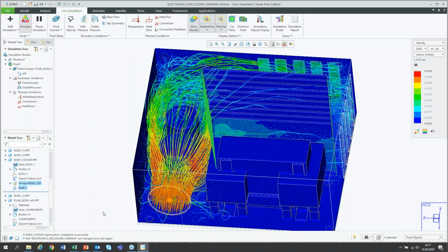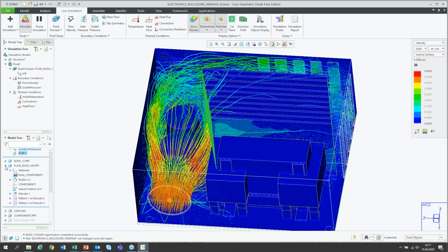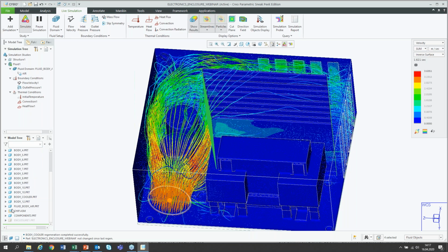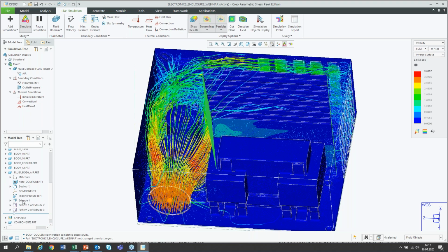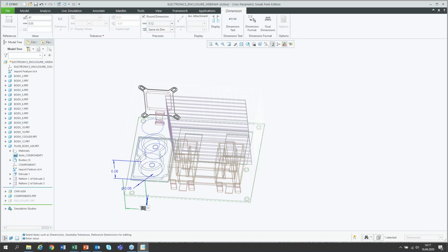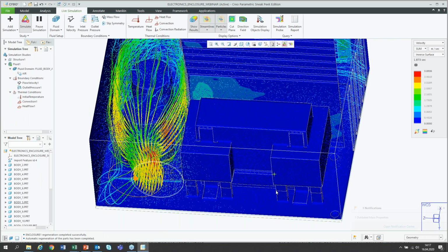And now I'd like to move the inlet here. This construction was built in a little bit a strange way. I have to change the fluid body to change the inlet. So I'm going here for that extrude. I'm just changing the dimension here from that 0.5 meters to that 0.75 meters. I have to hit here regenerate in order to see, let's say, the changed dimension.